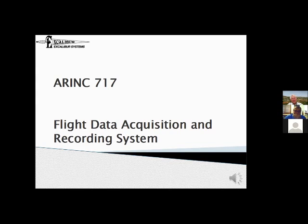Anyway, ARINC-717 is also used on commercial aircraft, but it's used for a very specific thing, namely flight data acquisition and recording systems, which are very closely related to black boxes. The idea is you want to gather data from all over the plane, compress it into a single data stream, and then send it on to the black box. So the black box reads ARINC-717, and there's a data concentrator which writes ARINC-717.